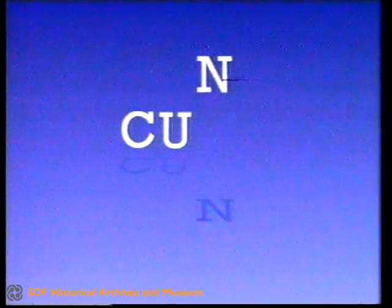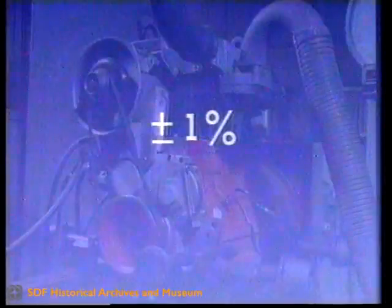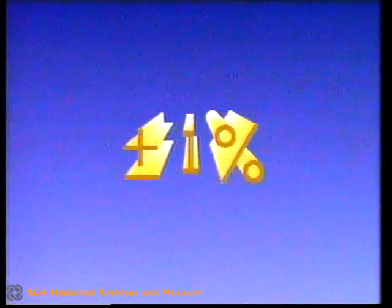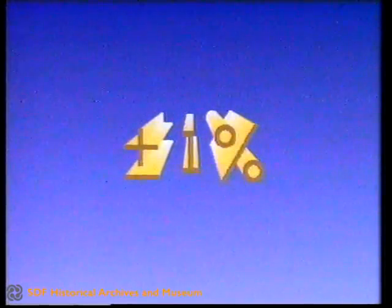CUNA standards. The tests carried out according to CUNA standards are essentially equal to those conducted according to DIN 7020. Only the corrective formulae for relating the performance figures to the standard conditions vary. The differences between the results of the tests carried out according to the two standards are generally within plus or minus 1%.